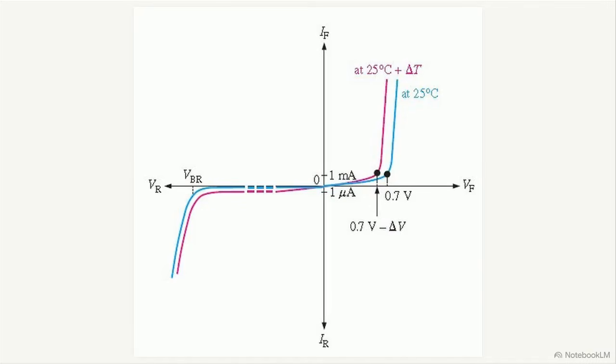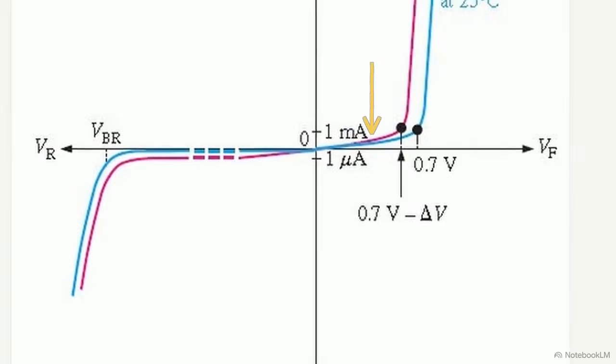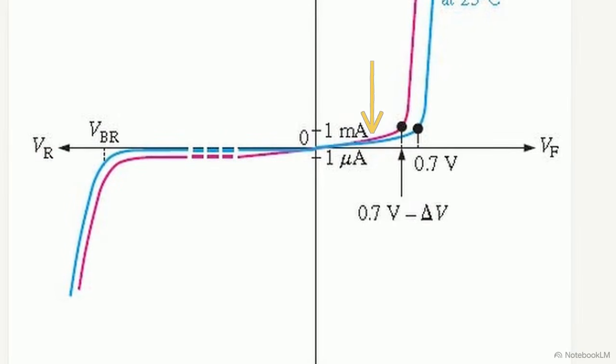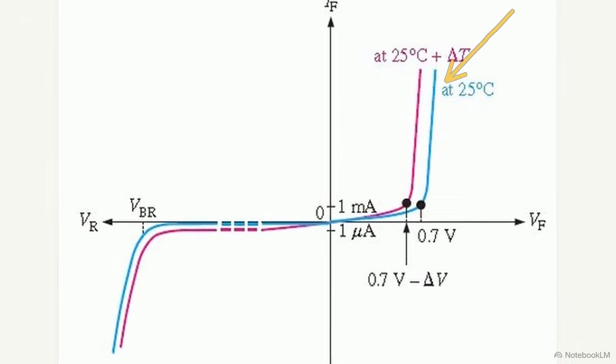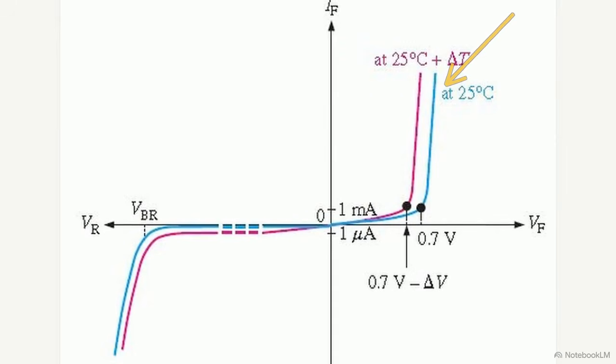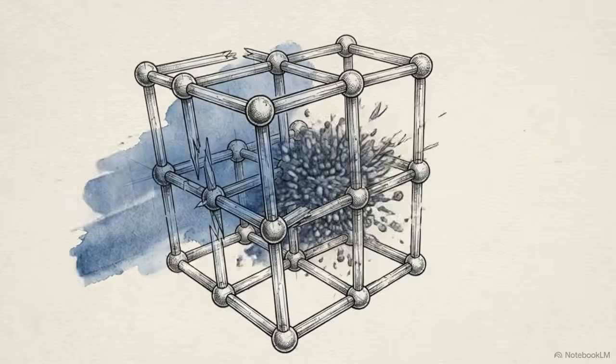This graph illustrates the voltage-current characteristic curve. Voltage is plotted on the x-axis and current is plotted on the y-axis. Under forward bias, looking to the right of the origin, the current remains functionally at zero until the voltage approaches that 0.7 volt mark. As the voltage crosses 0.7 volts and the barrier collapses, the current rockets upward exponentially. Under reverse bias, negative voltage results in a flat, near-zero line, representing only that tiny thermal leakage current.